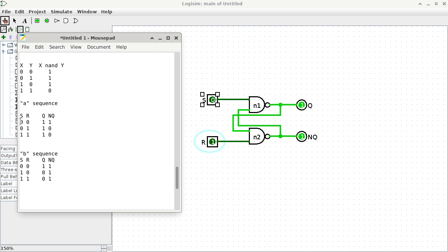When both input pins are zeros, both output pins are ones. Not a problem. It is consistent between the two sequences, right? The second step is different, but then you can say, well, that's because the input pins are different, so we can expect the output pins to be different as well. Not a problem. But look at the third step. In the third step, both sequences end up with 1, 1 as the input, but yet the outputs are different.